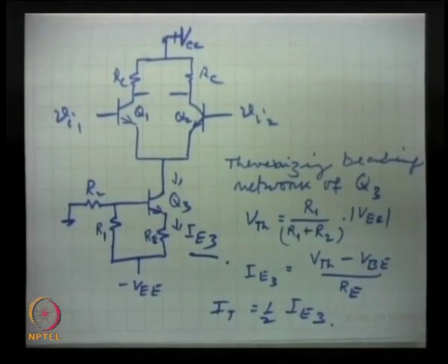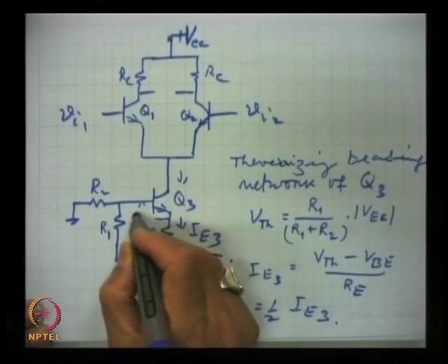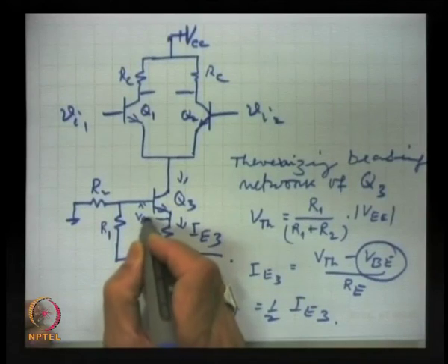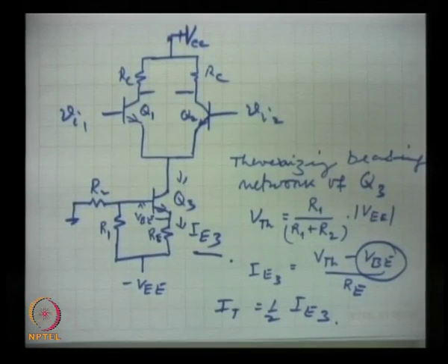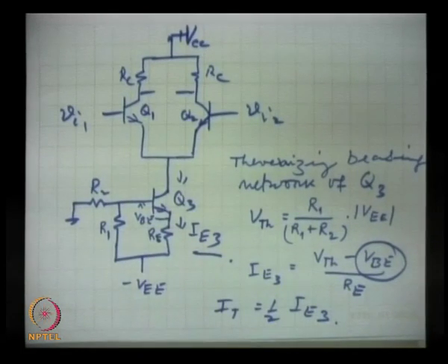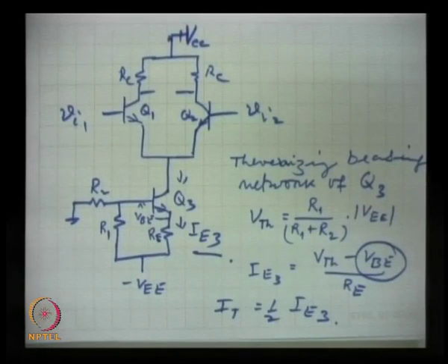Now, in this arrangement, which is very widely used, we have taken care of one factor, and that is of the current source. This current source will have much higher source resistance in comparison to the previous arrangement, but still there can be some variations, because of this voltage VBE, which is temperature dependent. It falls 2.5 millivolt per degree. So, if this input voltage VBE varies, that will vary the IB of this transistor, and hence IE will vary because of temperature variations.